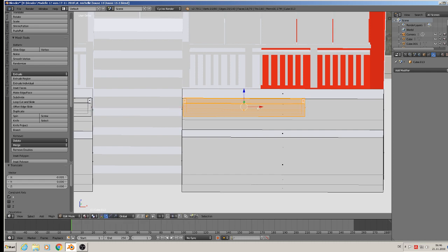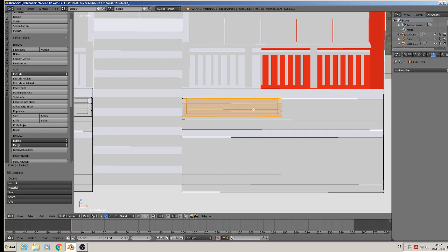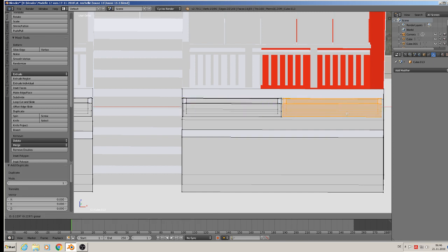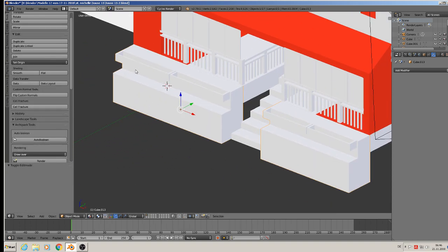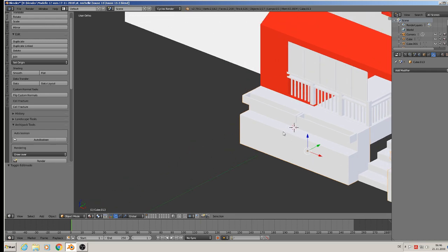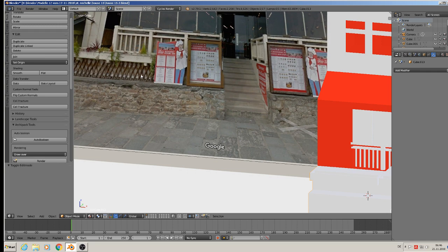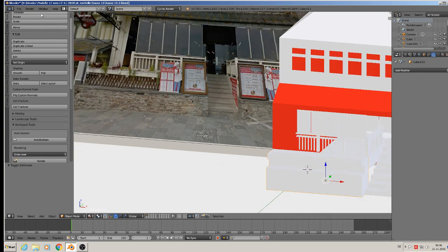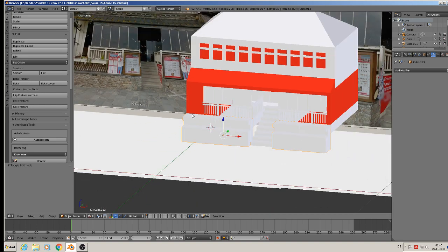So we place it there, take the vertex selection, make it to the half, then L to select the object, Shift D, and place that other one there. So we have that flower stuff there, we have that here, and you see between that there's space for this railing stuff there. Good.